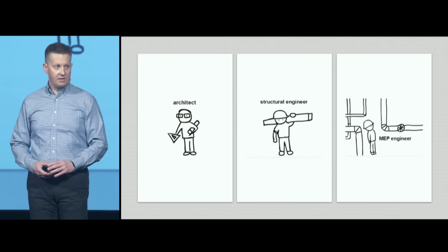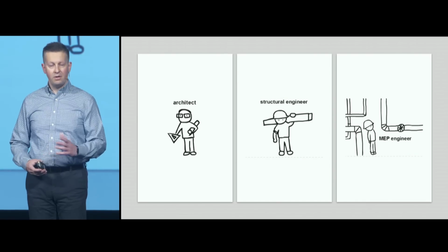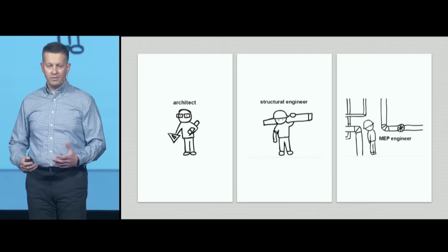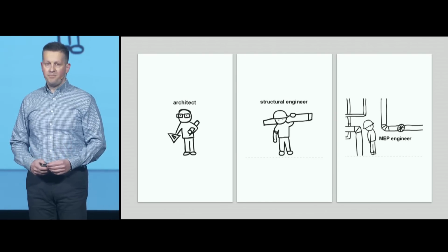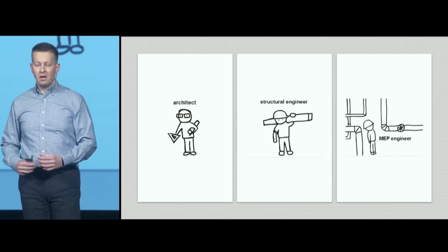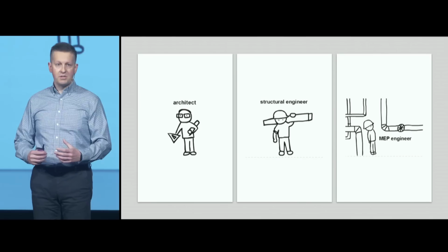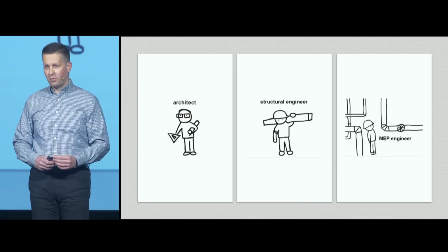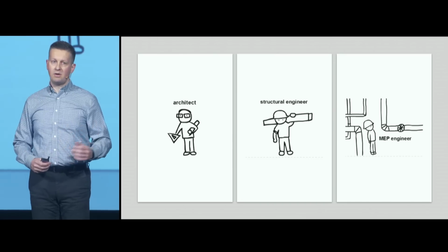Then the whole thing gets tricky when the MEP engineer comes into the picture. At that time, you have to go down to the element level, and you coordinate your work with a peculiar type of element, which is an anti-element, I would say, the void, the mechanical void. How you do that is called a special workflow provision for voids. So the mechanical engineer figures out where these structures need to be broken through, and then sends provisions for voids to the structural engineer and the architect.